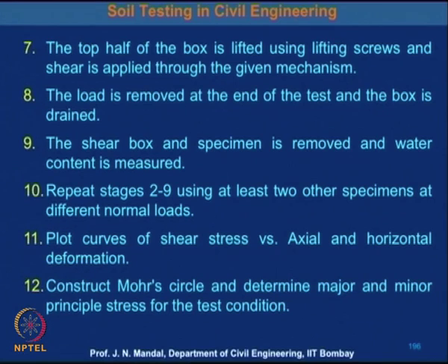The load is removed at the end of the test and the box is drained. The shear box and the specimen are removed and water content is measured. Repeat stages 2 to 9 using at least 2 other specimens at different normal loads.